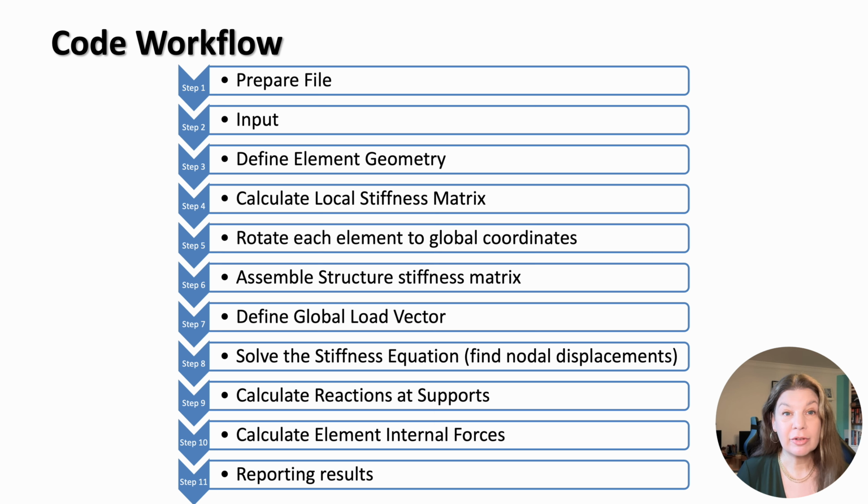So in this final version, all of the input information is grouped right at the beginning. So things like the node coordinates, the connectivity, material and sectional properties, loading, etc. It makes it much easier to see where everything goes and adapt the code for other structures. And just to be clear, this reordering doesn't change the method at all. It's just cosmetic and just makes the script more user-friendly.